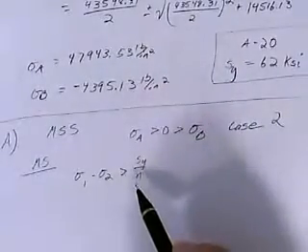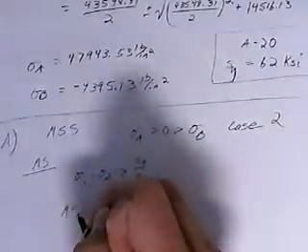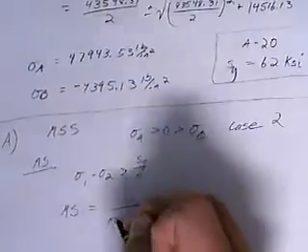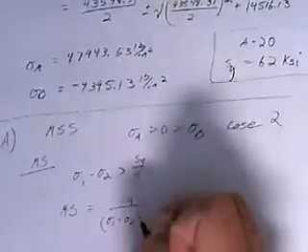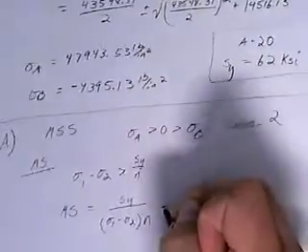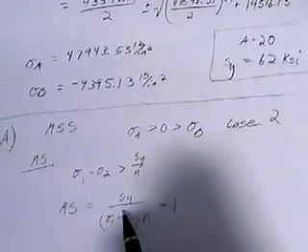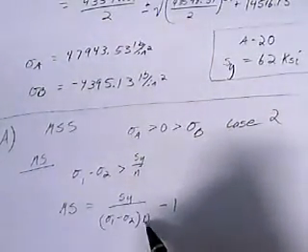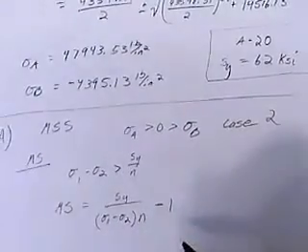So what this is, we're going to change this equation a little bit to MS is equal to Sy all over sigma 1 minus sigma 2 times n minus 1. And this is the factor of safety, so the allowable over the predicted times the factor of safety minus 1.